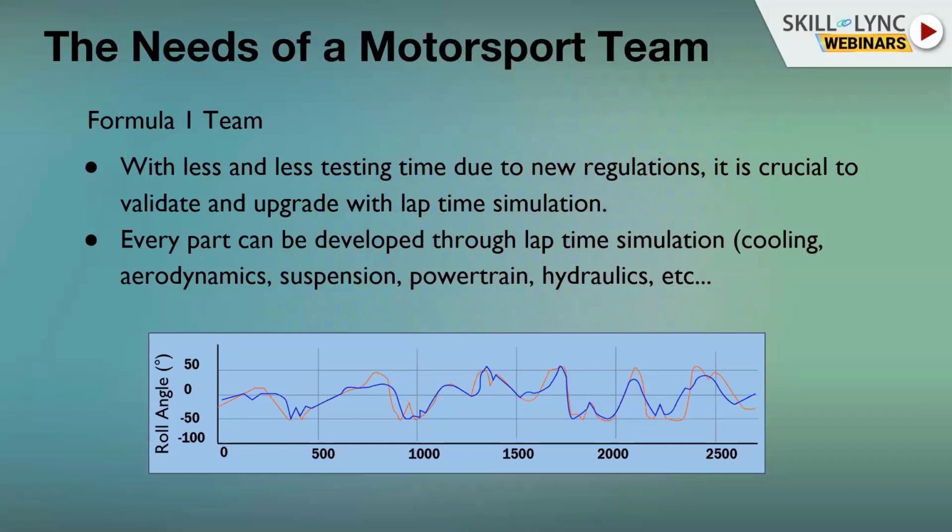But in that sense, when you are an engineer trying to develop a Laptime simulation, it's your job to search for what is missing in your equations or what is missing in your models. And in this very example, it was tire related because we were missing the stiffness of the tire. But you can see that when you are almost matching the data on the track, there's not much testing to do, and it's not necessary because your simulation is sufficient to be able to work around different solutions for your race car.